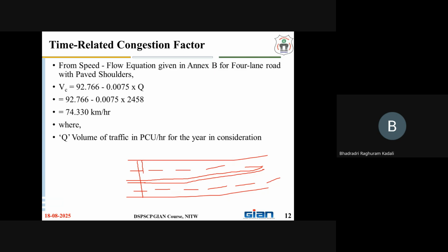Let us assume this is the stretch of the speed I am taking. Then I find that the speeds are very high, maybe 100 kmph they are traveling. Most probably, if you estimate the speed of a vehicle of any category or type at any point of time, this section is traveling at about 100 kmph. But at this point, the speed is not that easy to maintain because of this kind of curve, or other aspects related to the specific location, the environmental factors, maybe gradient, rise and fall, or the roughness of the section.